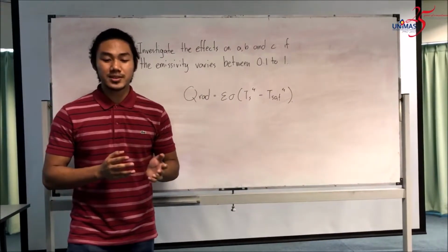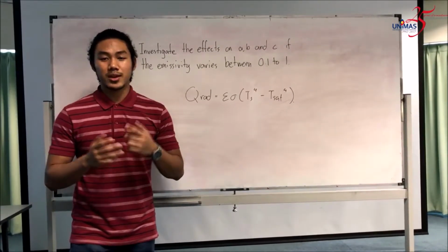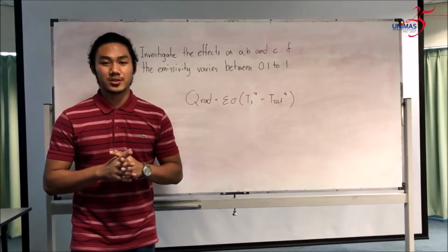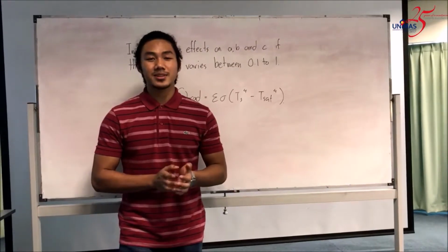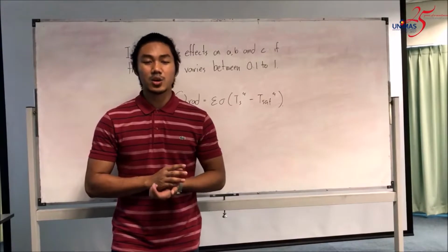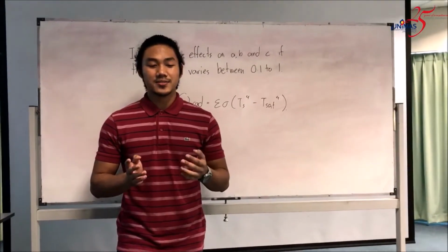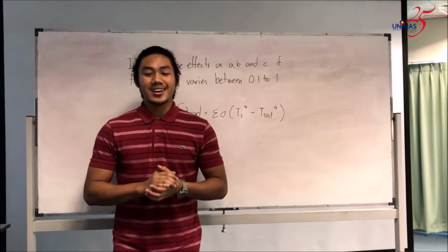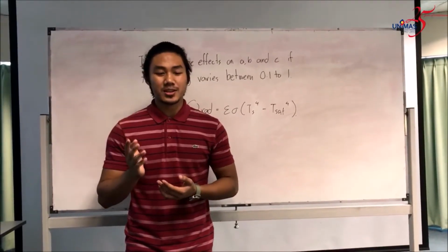Ideally, in the boiling process, the main focus is to transfer heat from the heating element to the water. However, this cannot be achieved due to some losses. Emissivity is one of the possible reasons for heat loss. Different materials have different emissivity. Polished metals usually have low emissivity, which makes them good reflectors, and rough surfaces, metals or non-metals, usually have high emissivity, which makes them good absorbers. A good absorber means the material absorbs heat better.